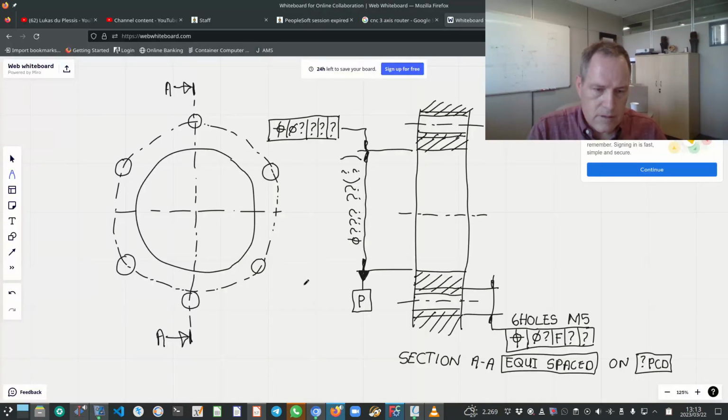Now, I would like to show you this sketch. It's a hand-drawn sketch, so it's not extremely neat. But this is the front view of that hole into which the bearing will sit. Then you can clearly see also the 6 tapped holes around that hole. And I've indicated the center lines and what is called the pitch circle diameter. Let me just type that out quickly.